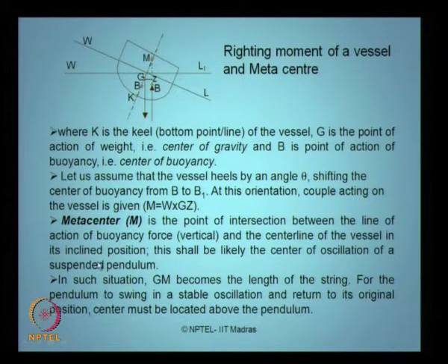Now the metacenter can be easily explained with this equation or with this figure. Metacenter actually is the geometric intersection between the line of action of buoyancy force, which is vertical, and the center line of the vessel in its inclined position. Let us say you project this line vertically up, and you project the center line in the inclined position, the point of intersection of these two will give me what is called the metacenter.